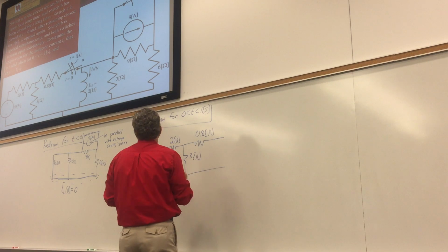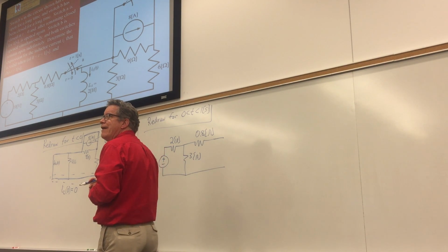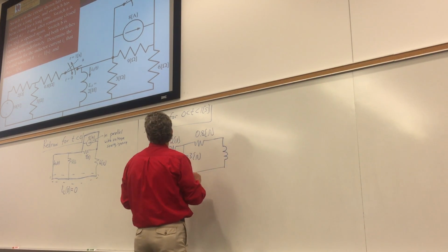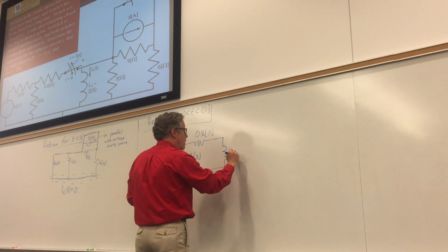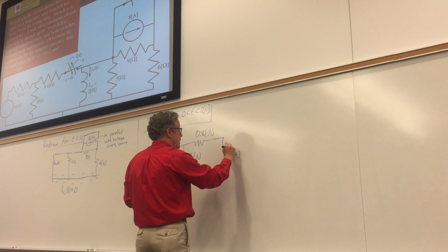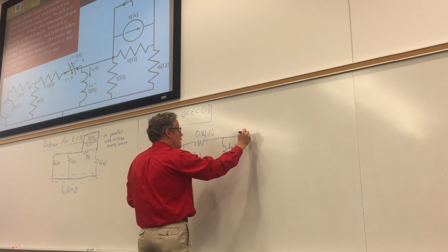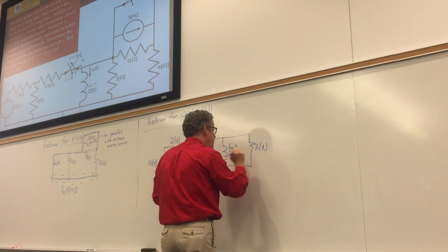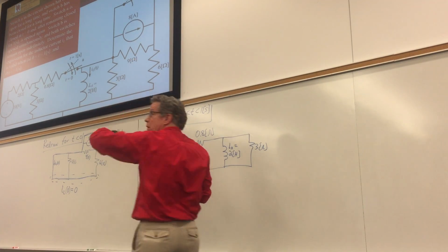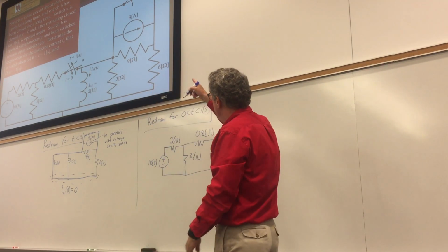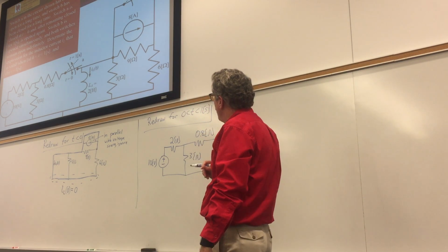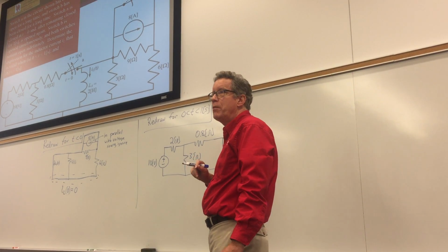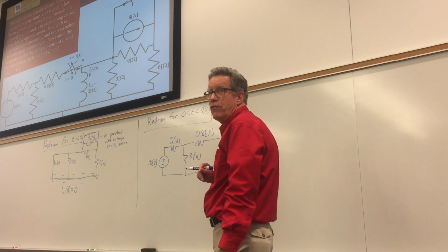The inductor. It's inducting in this time period. Draw it as an inductor. 2 Henrys. LA, 2 Henrys. Then 3 ohms. And look, he already gave us a hint that the 9 ohm and that 8 amp current source, they are both in parallel with a voltage source. They can be neglected with respect to things outside that parallel combination.